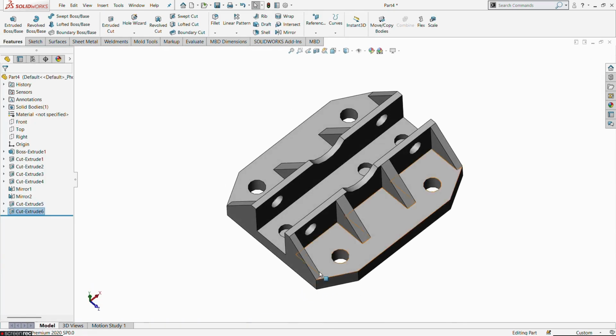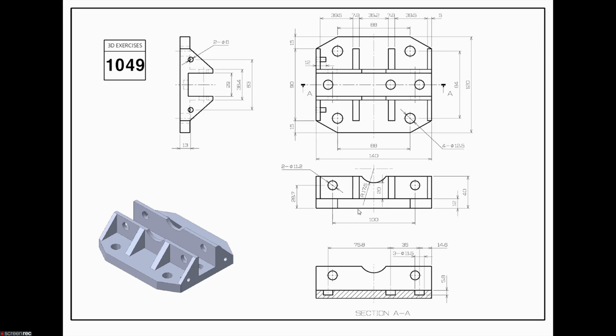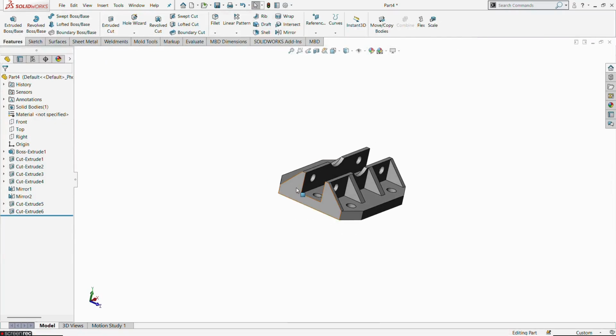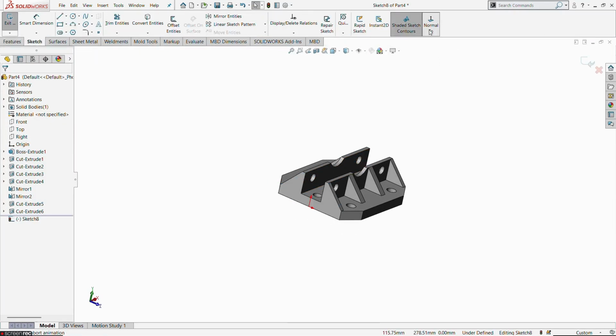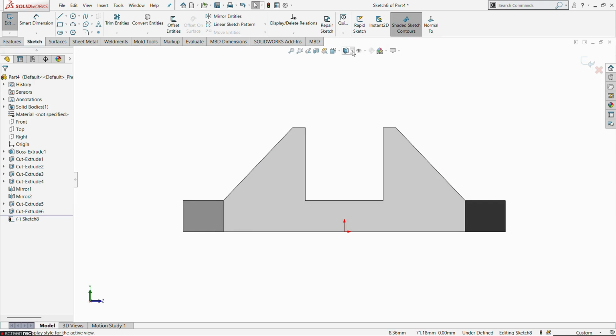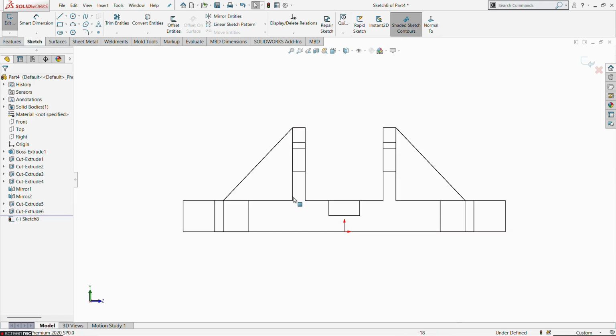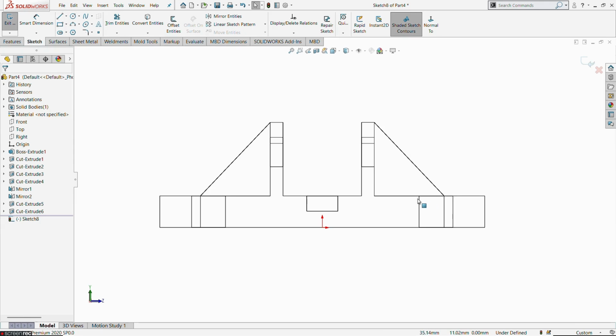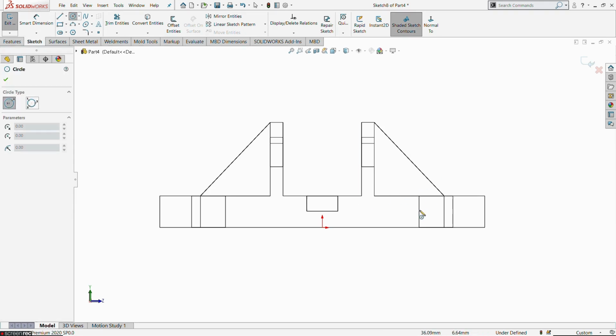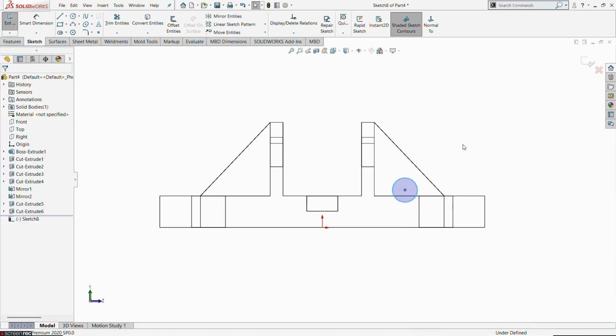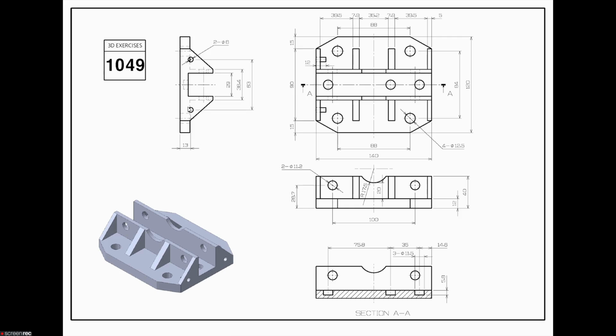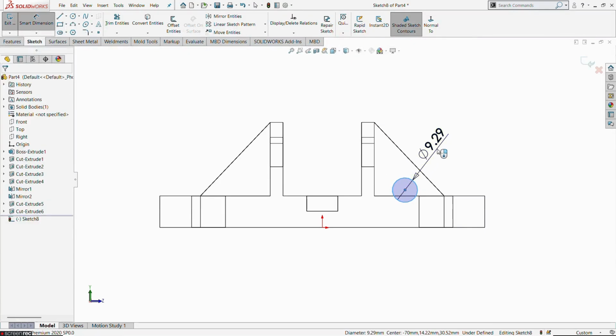Once we form the pocket, at last we are going to draw one simple circular profile to create new sections on these portions. So select these faces. Now we are going to create the last sketch on these portions. So let's draw profiles. Prefer this right area and draw one circular profile randomly, then fix it using small dimensions. What is the diameter of the circular profile? It is 6 mm. So mention 6 mm.